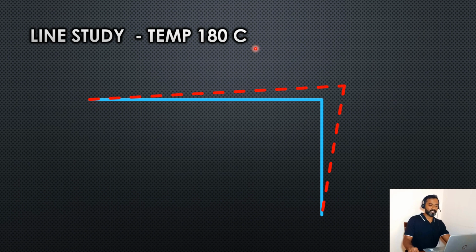So during thermal expansion, because here it is connected, right? So it is not free. This one end is not free. The line may be turning here, it goes up actually. So since it is connected, the line will take that as a restraint and it will move on the opposite side. So this is how the line is going to expand in any case if you have a bend like this actually. So how are you going to control it?